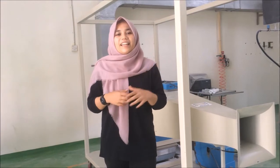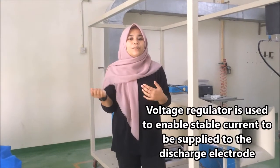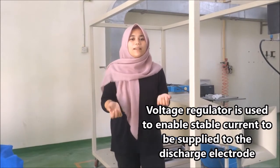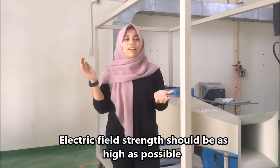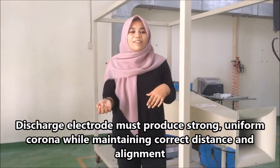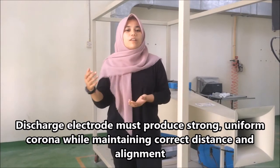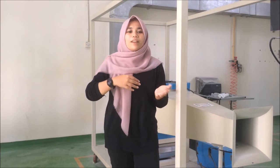The third factor is electrical sectionalization. A voltage regulator is used to enable stable current to be supplied to the discharge electrode. The electric field strength must also be high without causing too much spark between discharge electrodes. The discharge electrode must also produce a strong uniform corona while maintaining correct distance and alignment to prevent imbalance of the electric field.